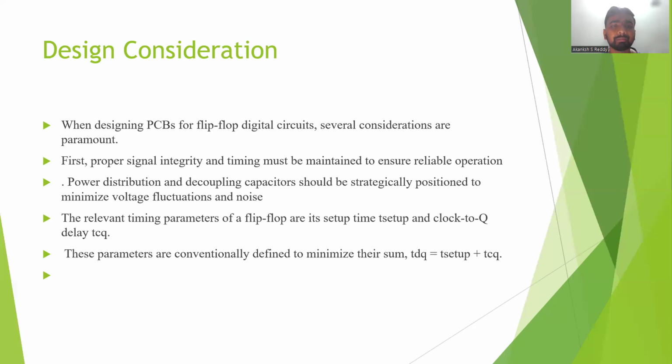The relevant timing parameters of a flip-flop are setup time T_setup and clock-to-Q delay T_CQ. These parameters are conventionally defined to minimize the sum T_DQ = T_setup + T_CQ.